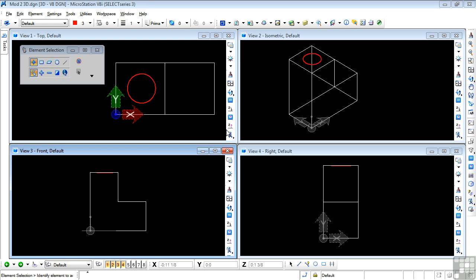You cannot see elements in front of or behind the respective clipping planes, and the active depth must be located between the clipping planes. You'll see how this works in a second. Think of the display depth as a thick sandwich. The bread on the top and the bottom represent the locations of the clipping planes, while the visible elements are represented by the filling in the sandwich.